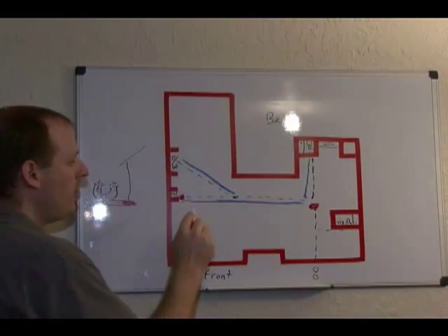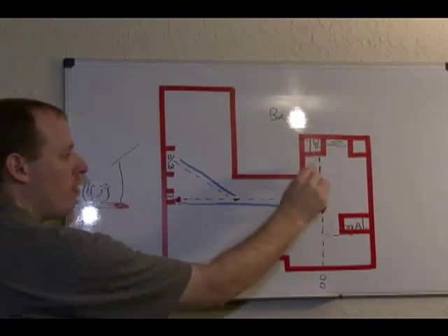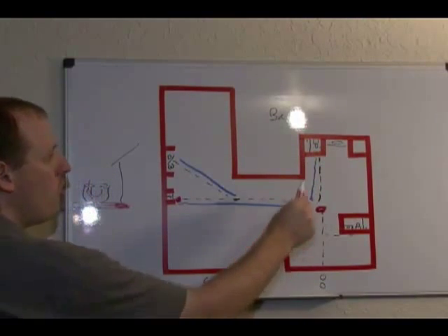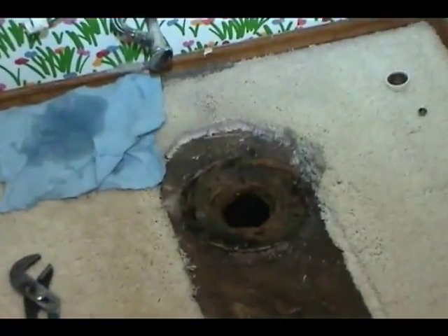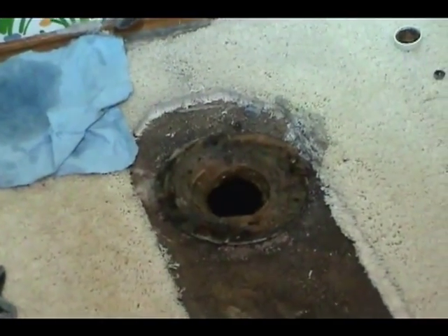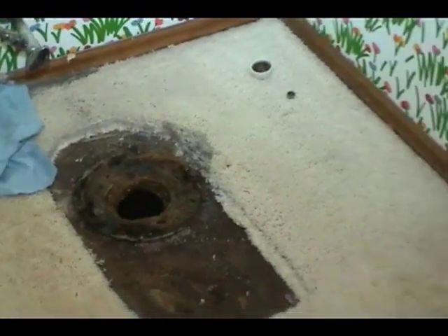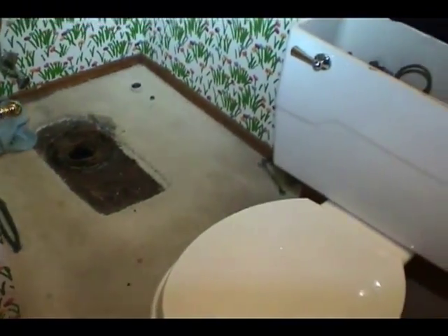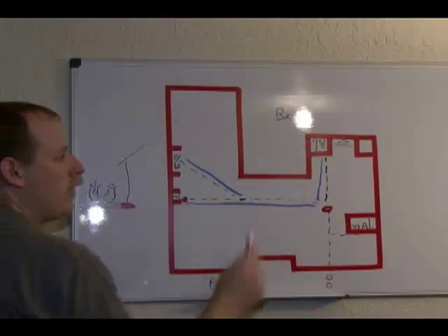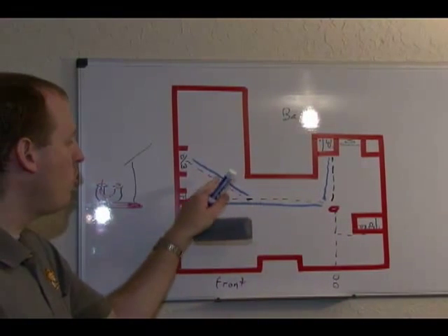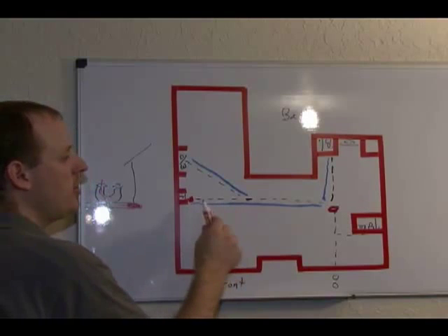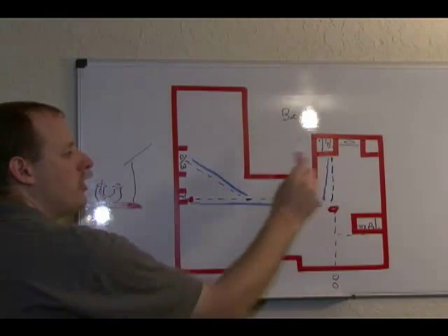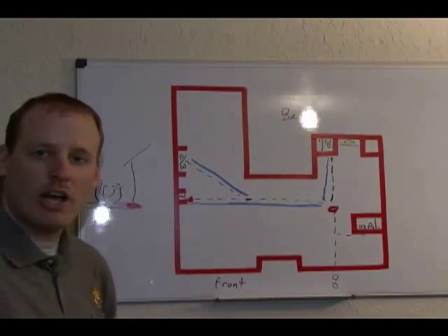At that point, because we did not remove the water from this line, we would then go back to our commode that was removed, and we're observing the water at that floor flange back there in the back for this illustration to be able to determine that there wasn't any leaks back here. We would then go back to this spot, fill this up with water again with this leak blocked off, and that then tells us that there are no leaks in this section of line.